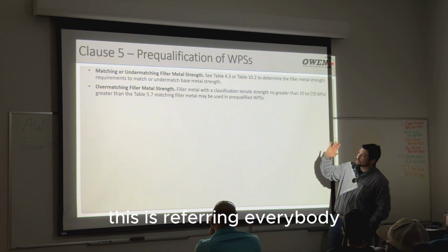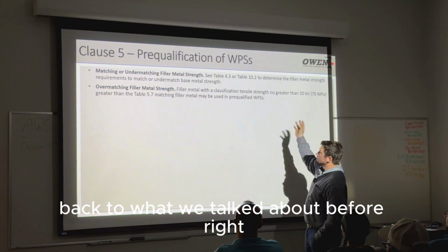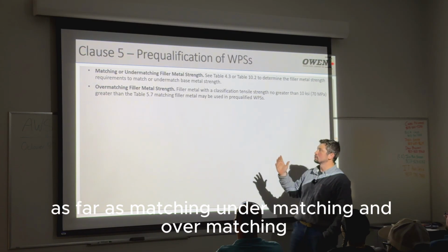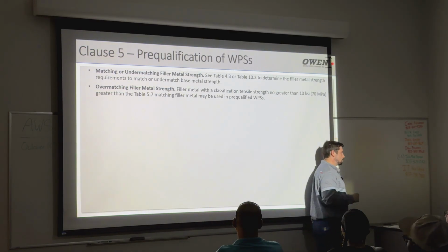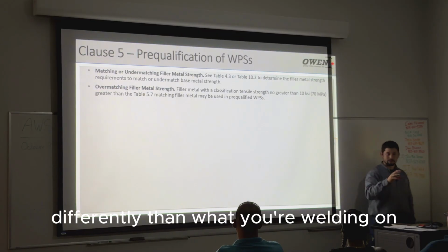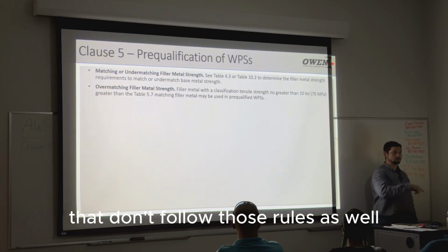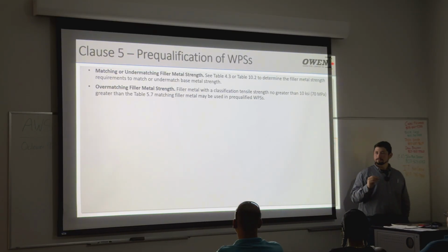Pre-qualification of WPSs, this is referring everybody back to what we talked about before, as far as matching, undermatching, and overmatching. Just like they don't want you to design joints to where your filler metal's too different from what you're welding on, they don't want you to design procedures that don't follow those rules as well.